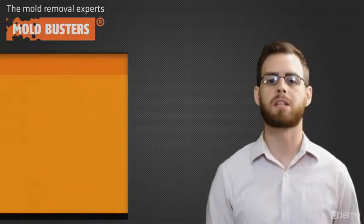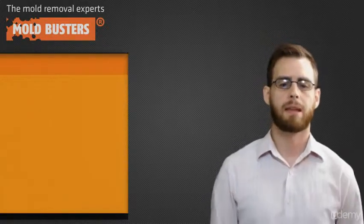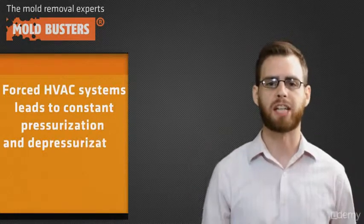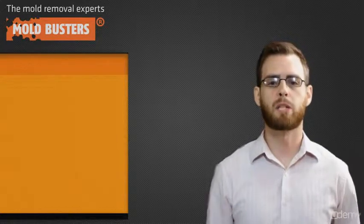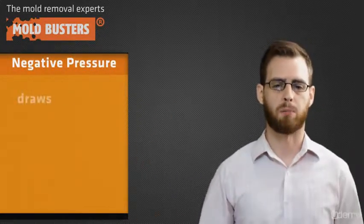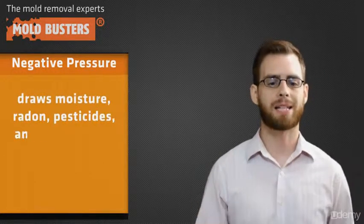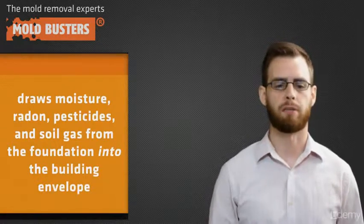Forced HVAC systems are usually constructed with numerous supply duct systems and one common leaky return duct. This system leads to constant pressurization and depressurization within the tighter building envelopes. The system creates what we call negative pressure. This negative pressure draws moisture, radon, pesticides, and soil gas from the foundation into the building envelope.